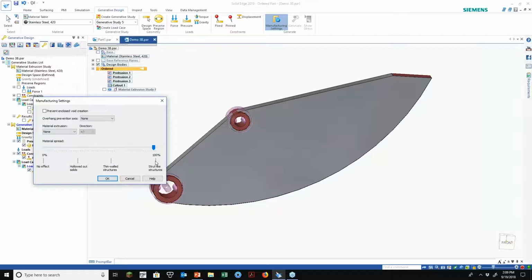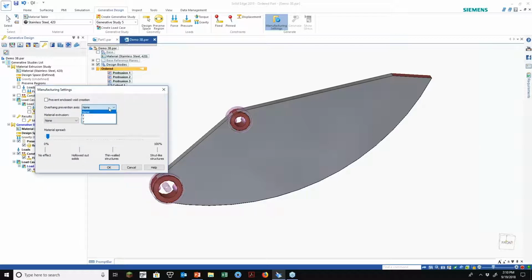So in SD10, the typical style was the thin wall tendril style. So it gave these long kind of weird little protrusions. Again, specifically for 3D printers, not a problem. For machining, impossible. So that's why they added this down here for continuous solid structures that would be machined. Then we have some options here to tell it how to create these features.